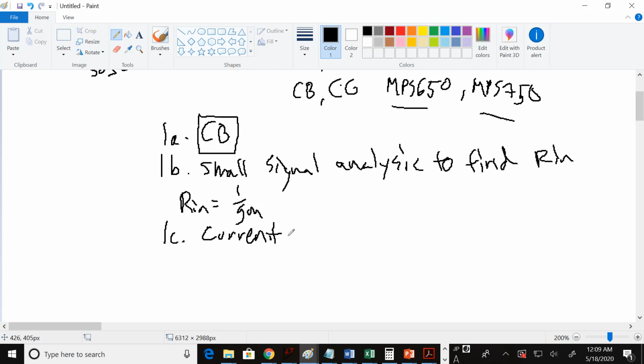So you always want to look at the transistor. They generally have lots of tables or lots of graphs where they show the range that they think the transistor works well. And you want to operate your transistor in a range that will make that transistor happy.